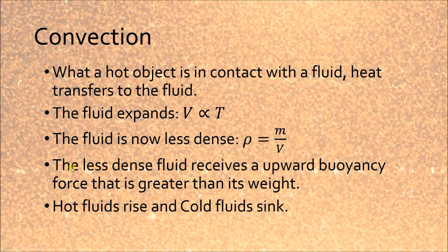And since the fluid now is less dense, it receives an upward buoyancy force that's greater than its weight. It's less dense than the air around it or the fluid around it, so it gets pushed upward and flows up. So hot fluids rise and cold fluids will sink. One thing to remember about convection is that this only happens in a fluid because the fluid can change density.